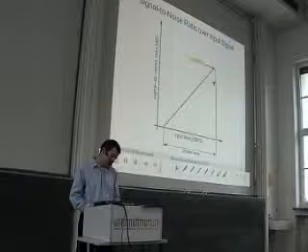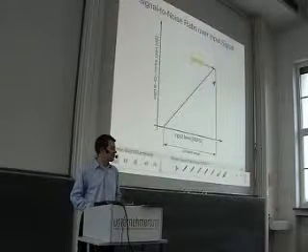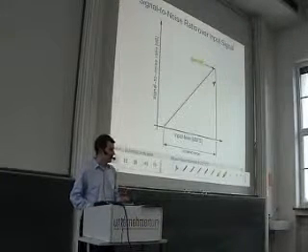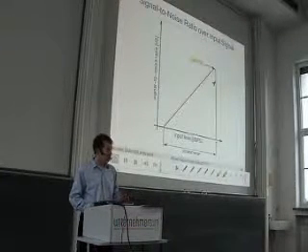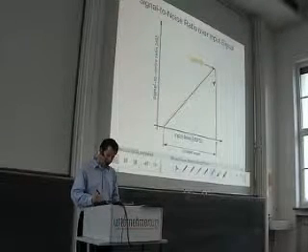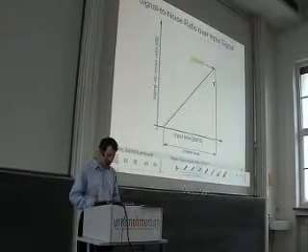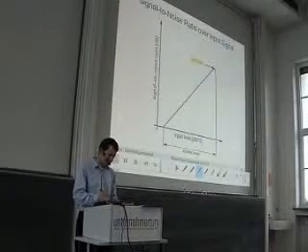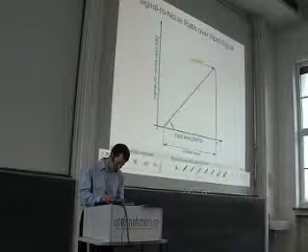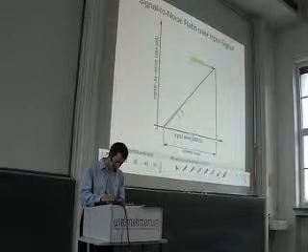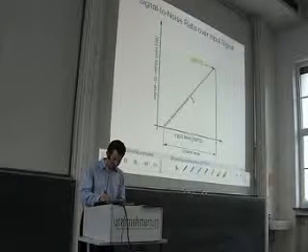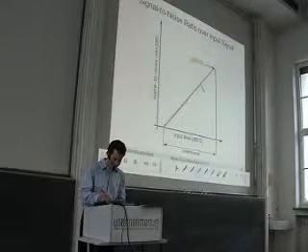Then if you get a curve like this, you always have to ask, is this the SNR that I see here, or is it the signal to noise and distortion ratio? Because if I also consider the distortion, this usually makes no difference for small amplitudes. Here the curve is the same. But if I increase the amplitude further, then the harmonics come into play.